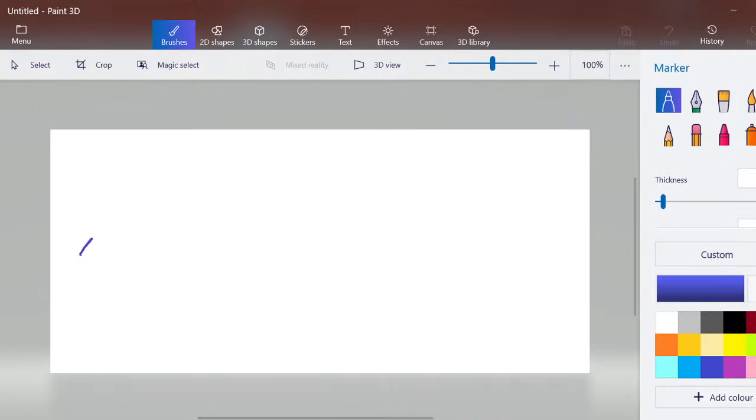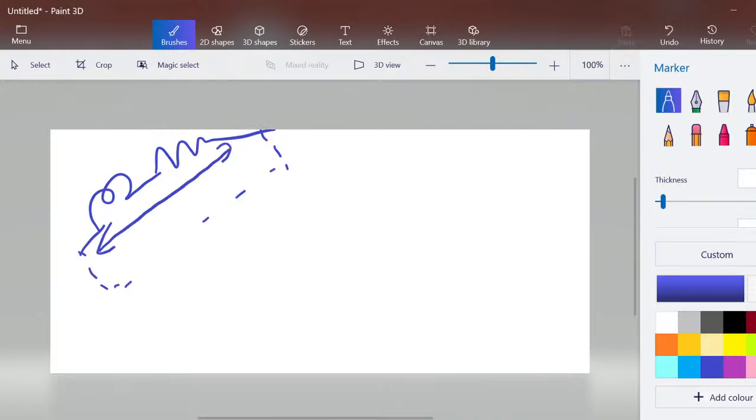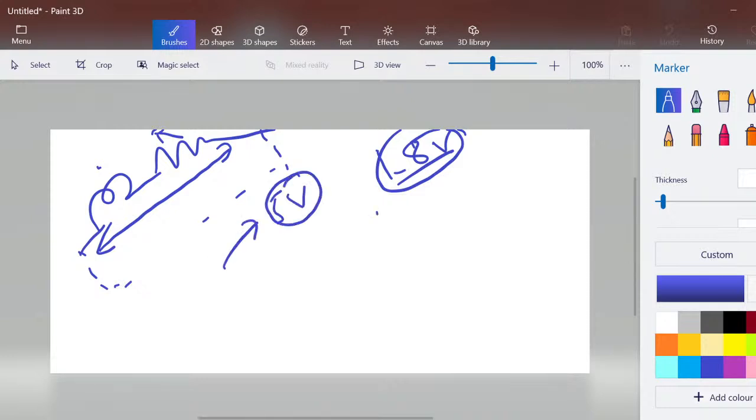Generally, take the circuit. This is the internal circuit, and we have to focus on these two components: this is the LED and this is the resistor. We have already said that the LED has a drop voltage of 1.8 volts. Whatever voltage is given from the digital pin, that is 5 volts, out of that the LED takes 1.8 volts. So what is the remaining voltage? That is 5 minus 1.8, that is 3.2 volts. Is it correct?